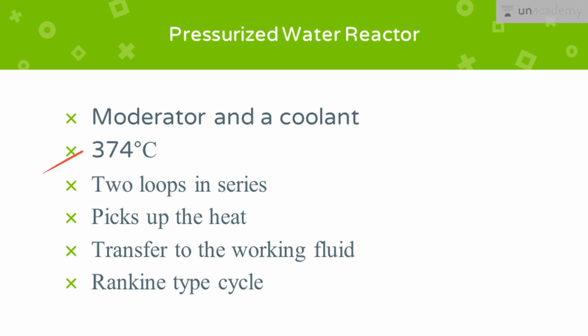In a pressurized water reactor, the coolant pressure must be greater than the saturation pressure, that is, the pressure corresponding to more than 300 degrees centigrade, to suppress boiling, and the pressure is maintained at about 155 bar so as to prevent bulk boiling.